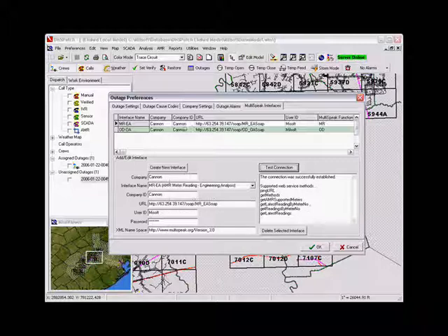We then select the ODOA, that is, Outage Detection to Outage Analysis interface, and also test that connection. Again, the Yukon server sends the list of supported methods. This setup only has to be performed once on one client terminal and is valid for all dispatch clients.